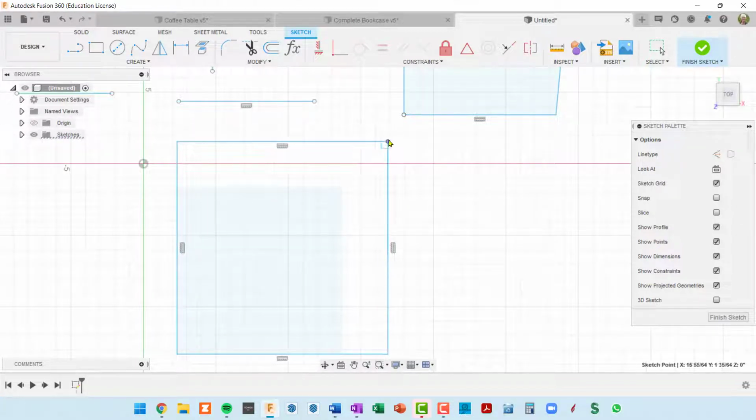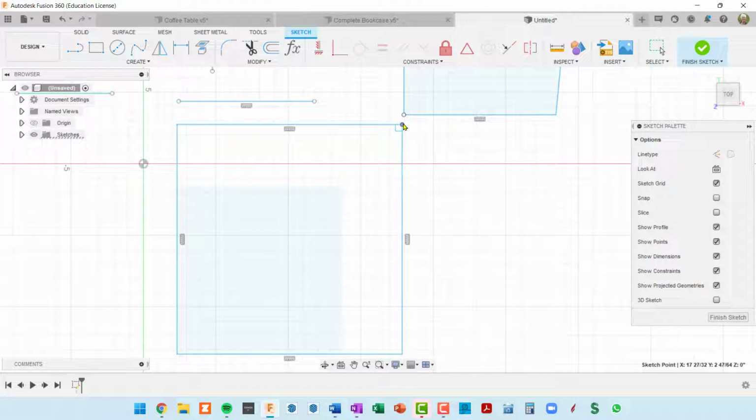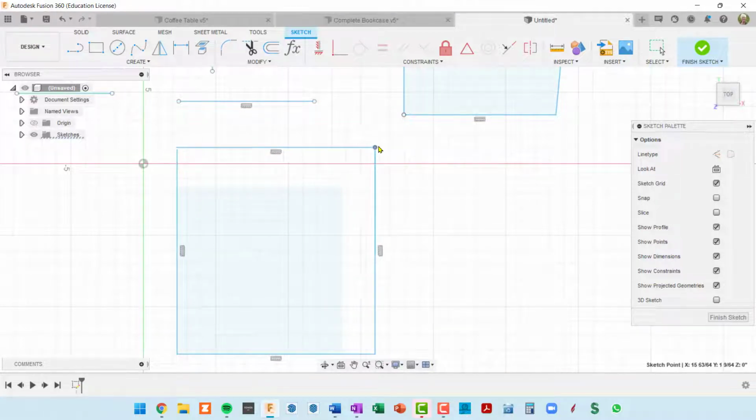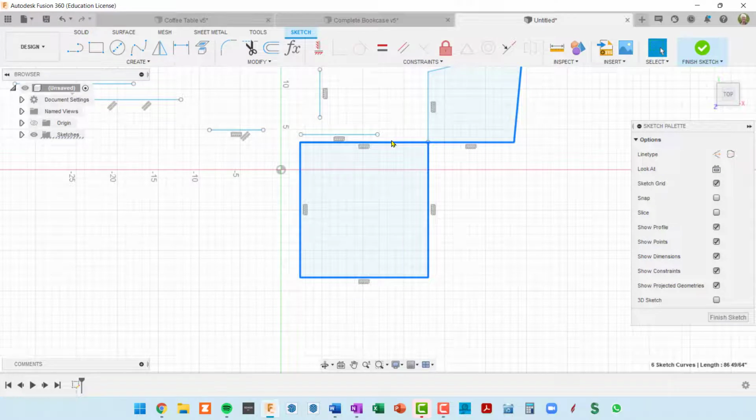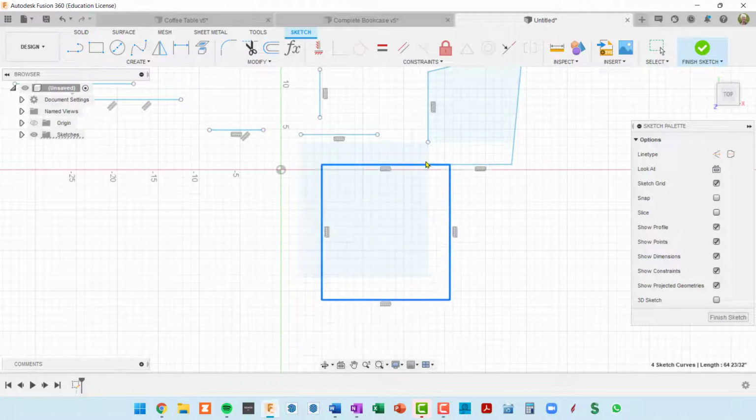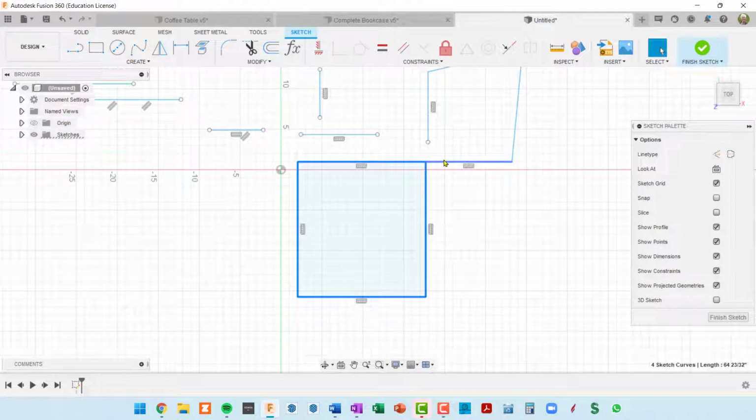So let's say I want this point to be coincident with this point right here. Two ways I can do that. I can move it up, and if I see this blue square pop up, I know I've imposed a coincident constraint. So if I release that, double click to get this rectangle and move it, you see I established one coincidence here.